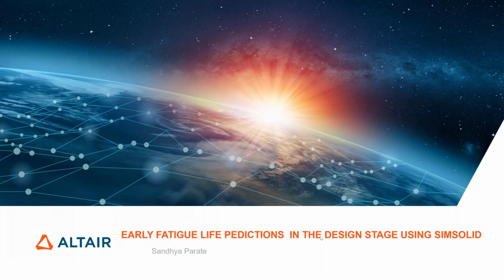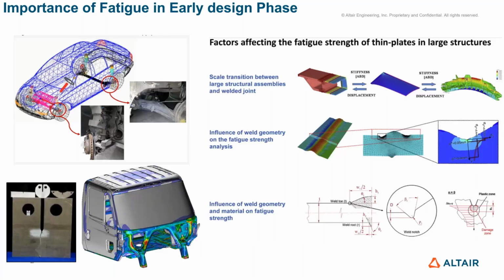So, what is the importance of fatigue evaluations in the design stage? It helps in identifying the critical areas, which allows for the necessary design modifications that will prevent failure during the operational life. It also helps to make iterative design improvements to extend the operational life. On the benefit side, it is cost effective if we realize the failures beforehand.